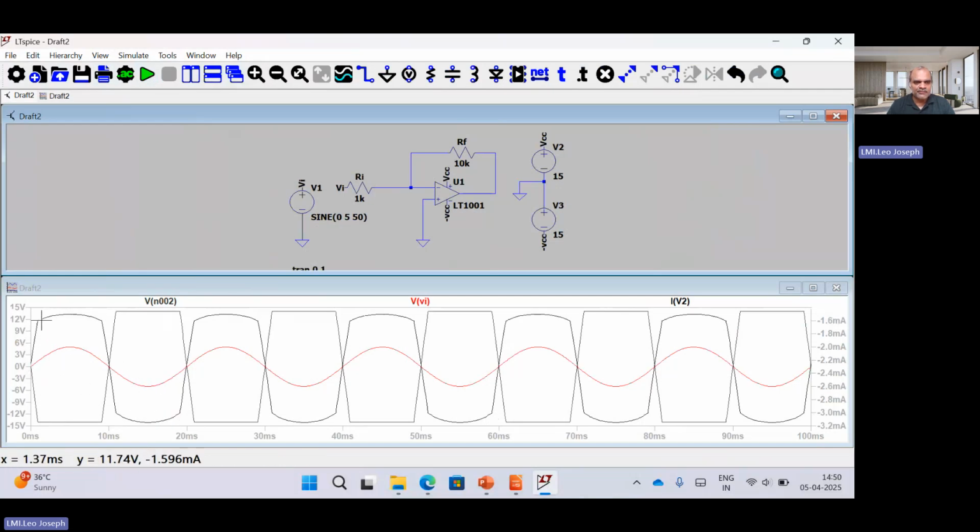But you can see here this square waveform. You can check here, this square waveform is clipping at minus 13.1 volt. What is our expectation? We have to get minus 50 volt here, but you are getting only minus 14 volts. Why? The main thing is that we are supplying a biasing voltage of only 15 volts. Whatever voltage you give, whatever theory you speak, depending on the bias voltage, the maximum capacity is all that will be conducted; the remaining will be clipped off.